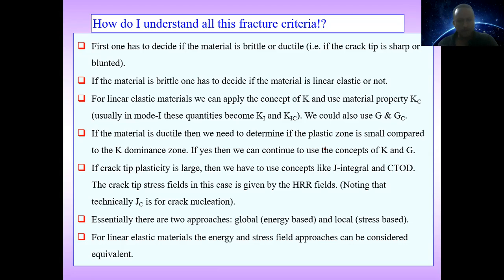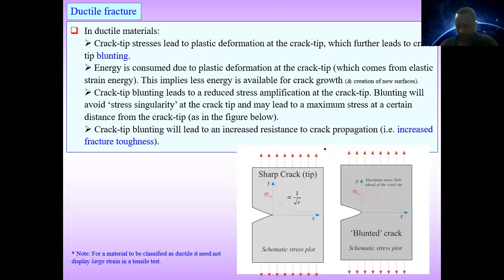Essentially, there are two approaches, global and local. Global is energy based and local is stress based, according to these two scientists based on their work. For linear elastic materials, the energy and the stress field approach can be considered equivalent.